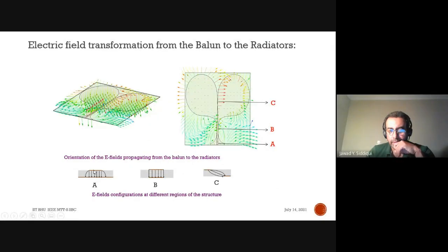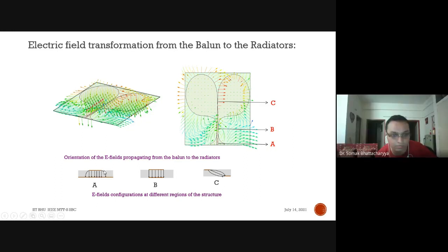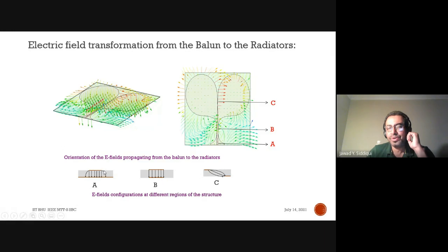Now, you know, this is how a microstrip line works, right? These are the electric field lines. There will be some fringing electric fields on the two sides, right? Yes. Now, when you have a fringing electric field on two sides, if you decompose it vectorially, you have a component of the electric field in this direction and in this direction, right? Because these are skewed electric fields. Yes. Now, when you have a skewed electric field, you will have a skewed magnetic field too. When you have a skewed magnetic field, you know that the magnetic field will be in this direction, in the very small and close region of the microstrip line.